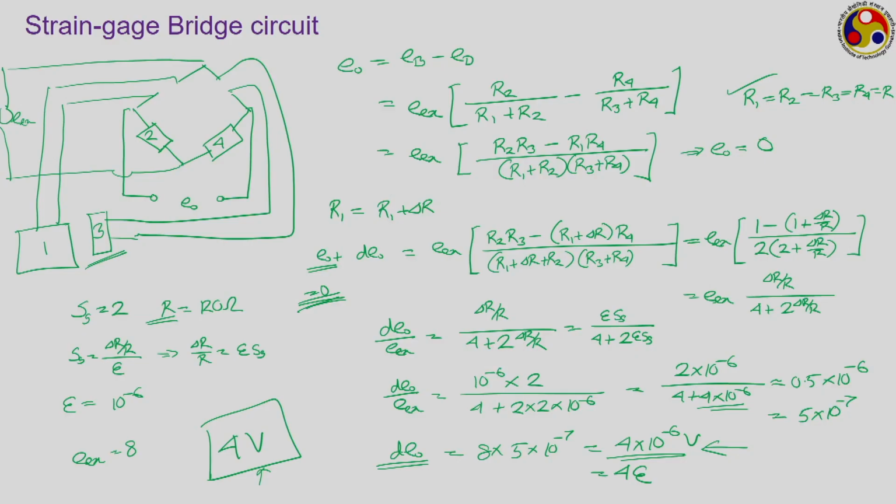That is why it is very important to keep this 3 at a location very close to 1, so that it is able to sense the same environmental condition. And now, whenever there is a change in the resistance 1 because of the change in temperature, 3 will also suffer an equal change, and that will get reflected equally in this particular relation, thereby not altering your final output voltage and giving your final output in a temperature independent way.